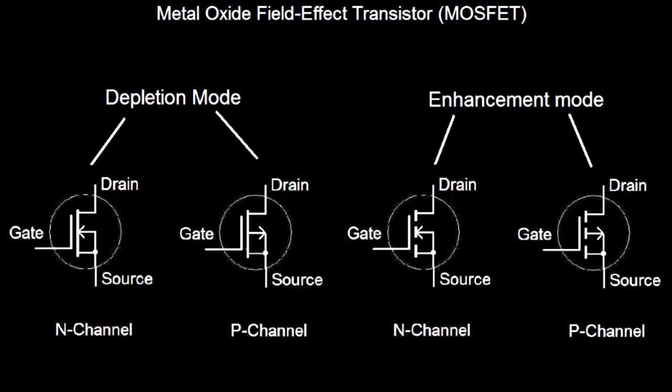Now, these things are very useful because the current is very little. We're talking about microamps or nanoamps. So these transistors can be connected directly to the integrated circuit without any effect whatsoever. And these pretty much have an infinite resistance between the gate and the channel. You can use these either as a switch, or as a voltage-controlled variable resistor. And believe it or not, these can be used in amplifiers.